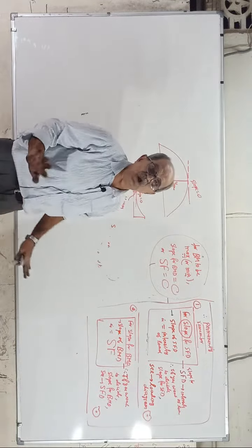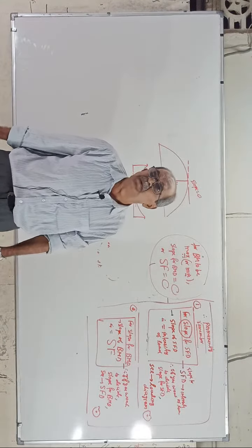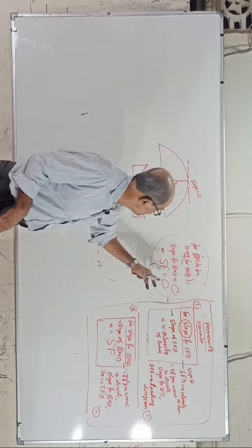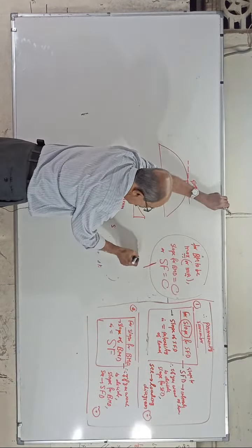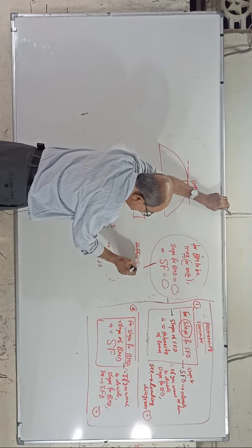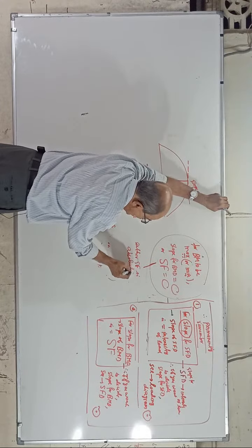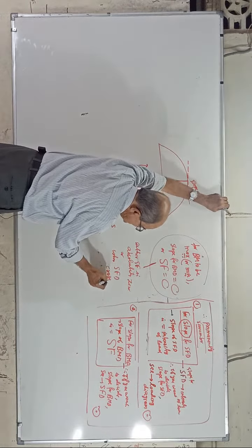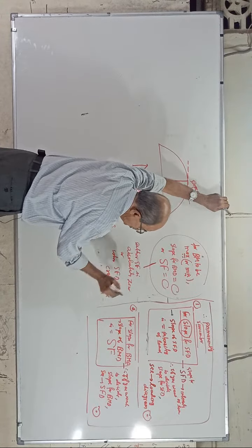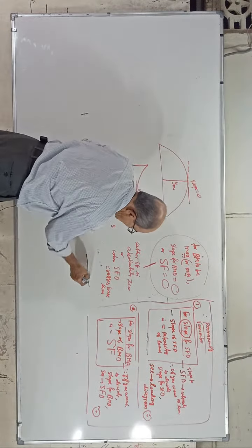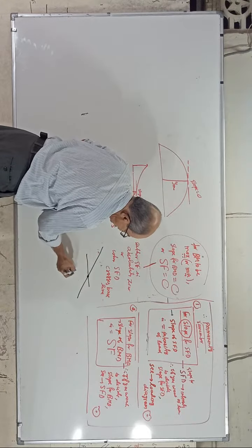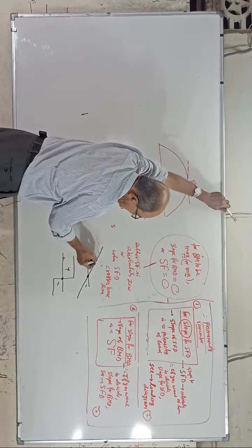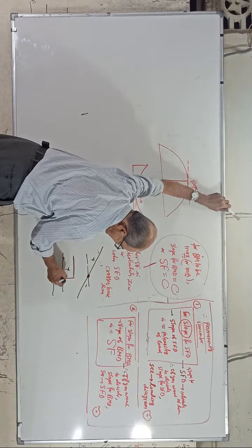Okay, now beyond the limit I will not go here. So remember, bending moment is usually maximum or minimum. It is called a local maximum, not for the entire beam. For that region where shear force is equal to 0, either shear force is absolutely 0, or you can say where SFD crosses the baseline. That happens under a point load. Either the shear force diagram should be 0, see here, 0, or this way, plus to minus, you can write here. Either it is absolutely 0, or it crosses the baseline.